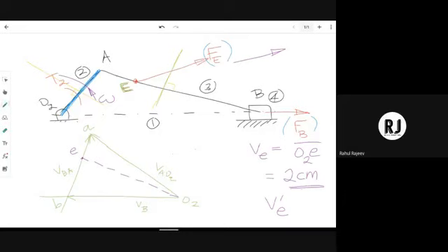You draw a velocity line which is parallel to FE. So, keeping your set square and scale, you draw a line like this. Now, what does this depict? This depicts the line of action of force FE. The line you have drawn has the same line of action as FE.